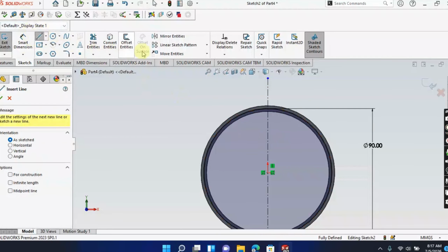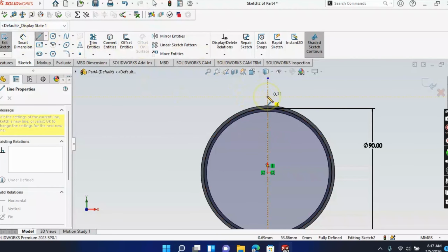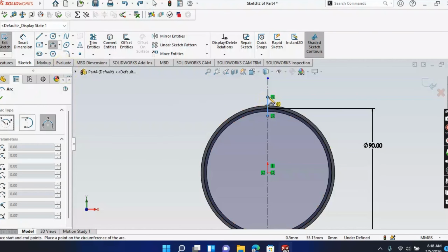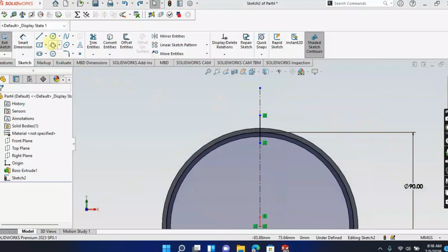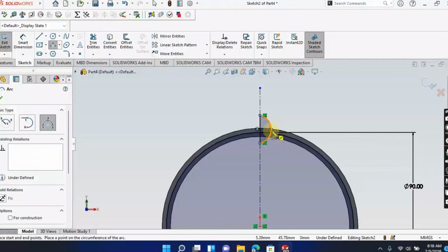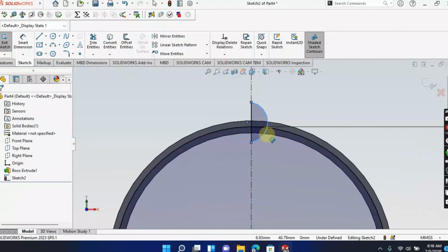Sorry, why is it not picking? So you draw a line right like this, straight down here, and then you now create what's called a 3-point arc. Let's create a 3-point arc. And then you create a 3-point arc from here, then pick it up to this particular point. When you see those red dots, know that there's a point there that you are trying to align with, then drop it like that. So you have this already.